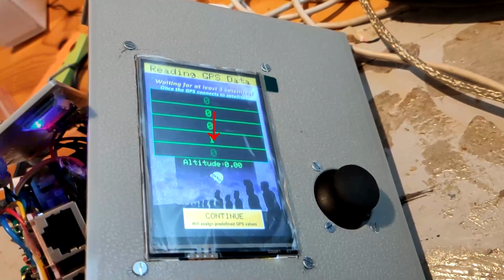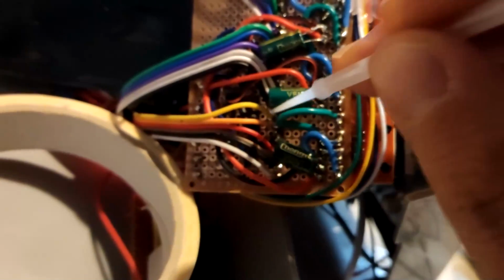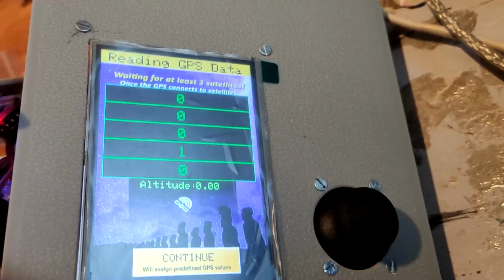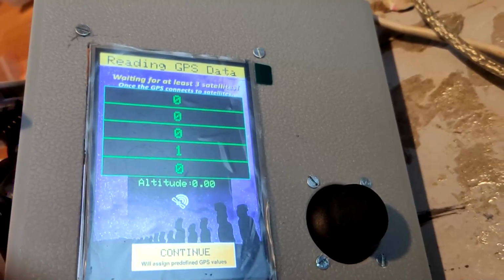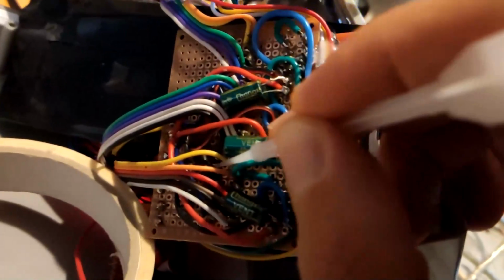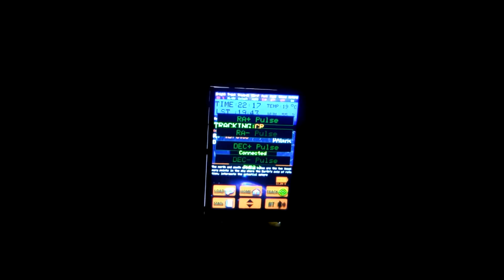The advantage of this is you can see the status of the pin directly on the screen when you are looking at the solders to resolve the problem. After that, some hot glue to fix the bad solder and it was okay. This firmware was only for DIAG purposes, so I reflashed the original firmware and all was okay.